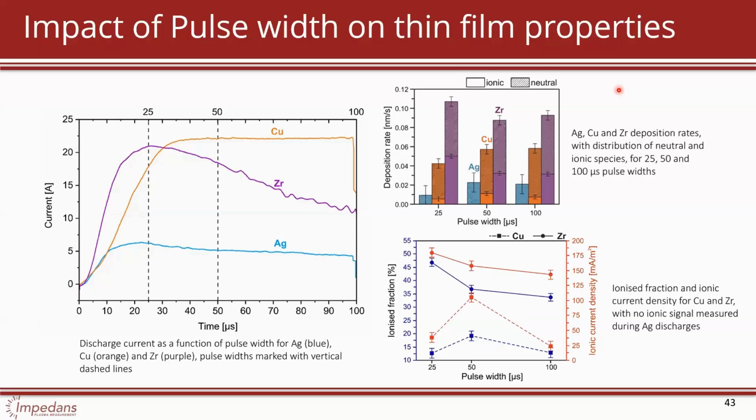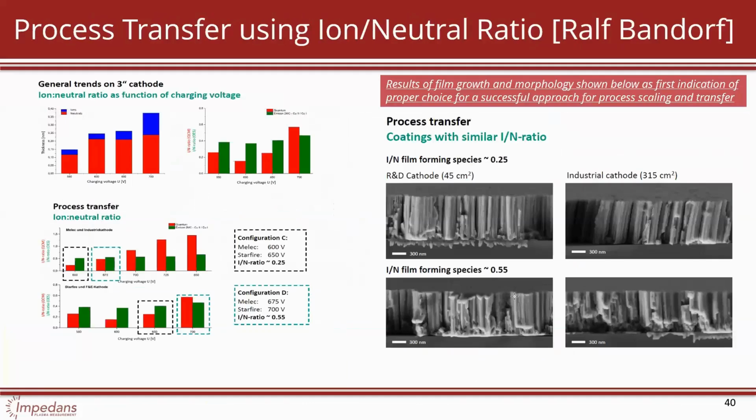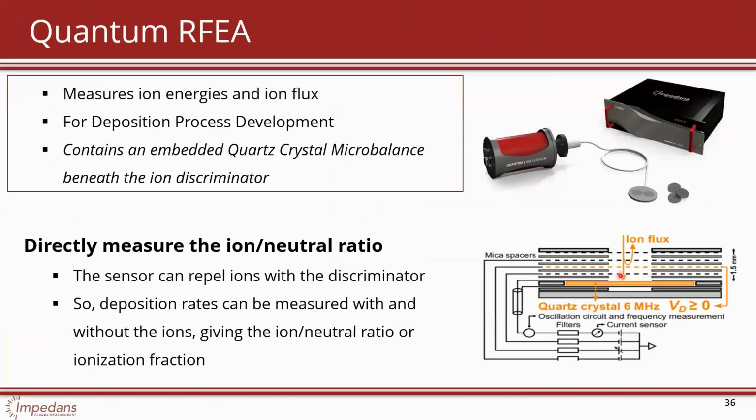So in terms of the ion energy measurements, they're completely repeatable. If you go from sensor 1 to sensor 2, it doesn't matter. The ion energy is always repeatable. Ion flux is different. Ion flux depends on the transmission of those grids. So if we go back a little bit, we look at this here. The transmission matters for ion flux because we're measuring current down here, but that has to pass through these grids. And if you're depositing, you are coating this up.